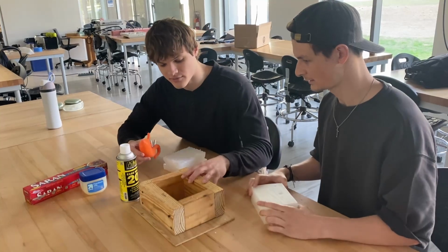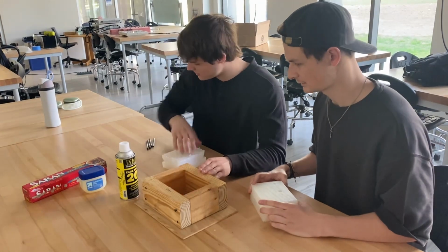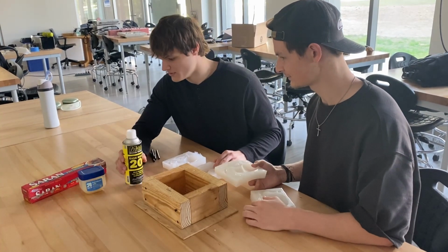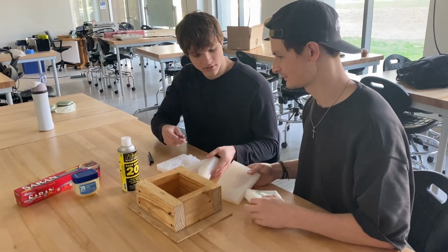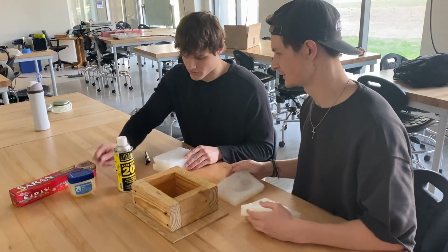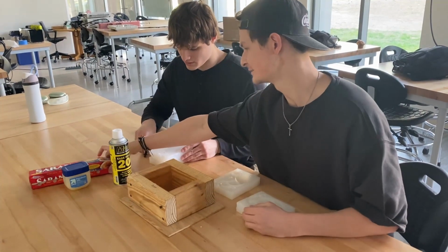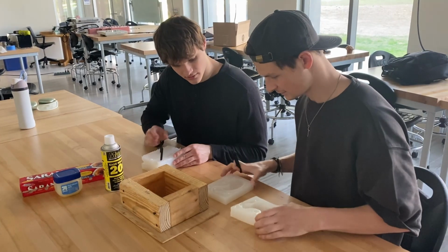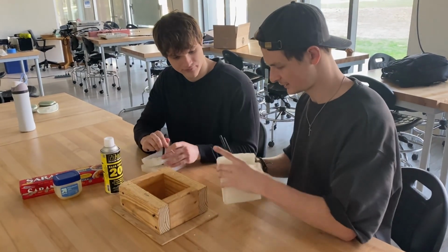In the beta prototyping phase, our challenge was to make the tunnel system easily accessible for inserting and retrieving foreign objects. We solved this by creating the model in 2 silicone halves that could be opened then resecured after each use. To make that work, we allowed the first layer of silicone to cure, applied a release barrier using petroleum jelly and anti-stick spray, then poured a second layer on top. This allowed us to separate the 2 halves cleanly. With the process refined, we moved on to a full-scale version.